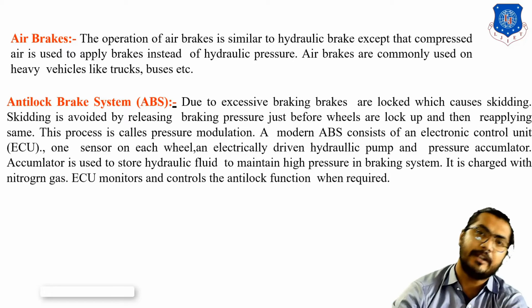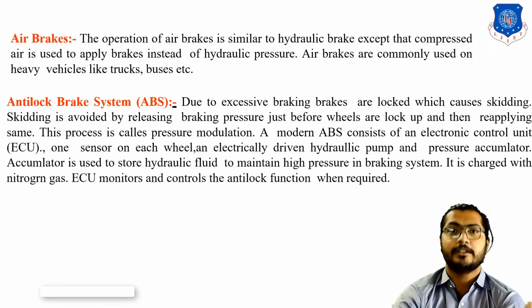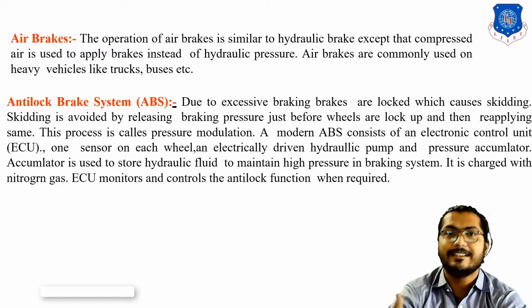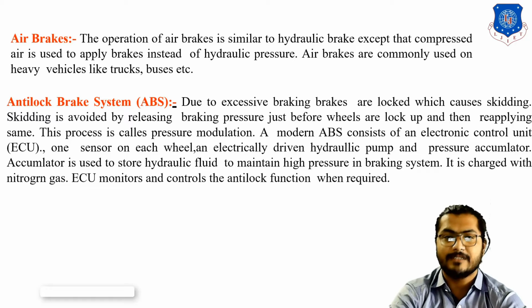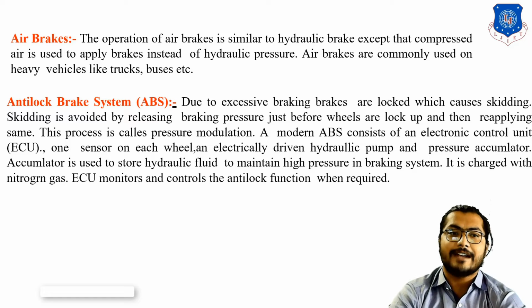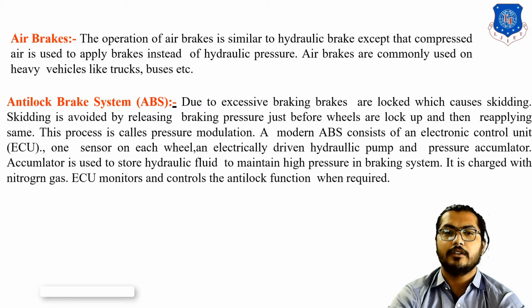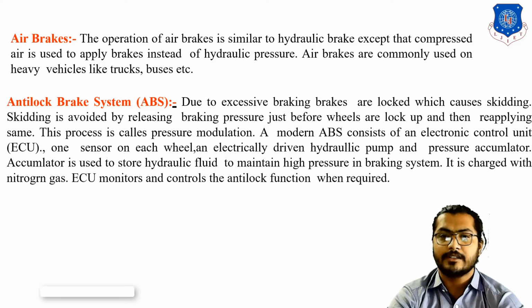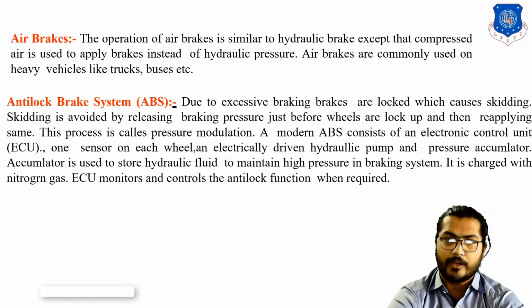The function of the accumulator, as we know from fluid mechanics, is to accumulate pressure and supply high pressure wherever it is required. It stores the fluid at high pressure, and it is charged with nitrogen gas. The ECU monitors and controls the anti-lock function when required.